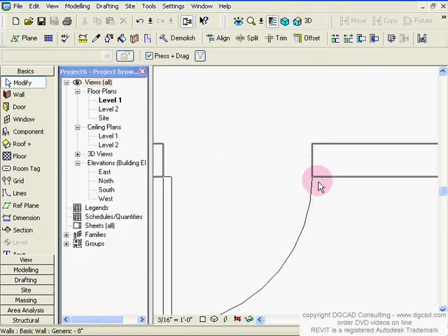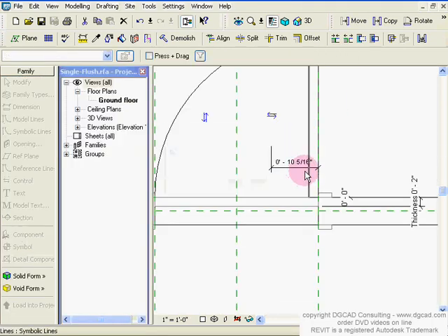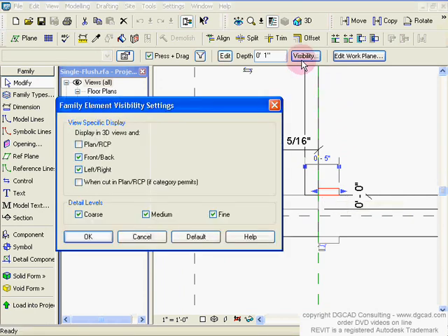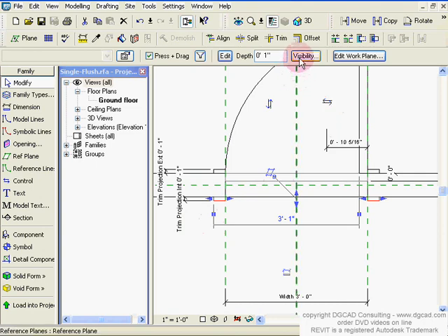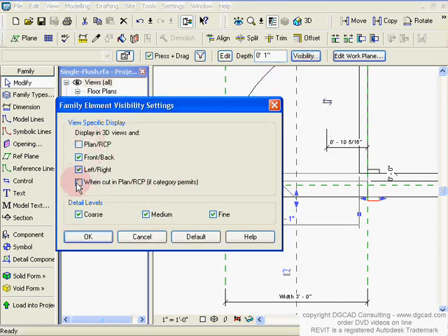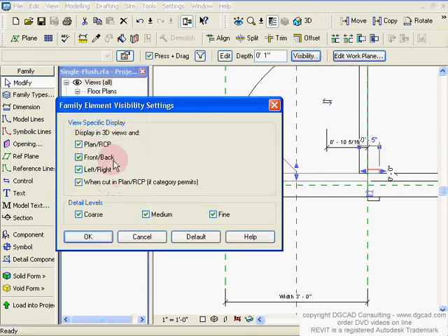If we go back to our project here in our main floor plan, okay, you'll notice it's not showing the frame, and that's because those mass elements right here are actually told not to be shown when they're cut. If you want them to be in there, you can put that on there. Okay, then you've got your same detail level over here. Now that is that extrusion. Okay, maybe you want to do the same with this one. Plan when cut.